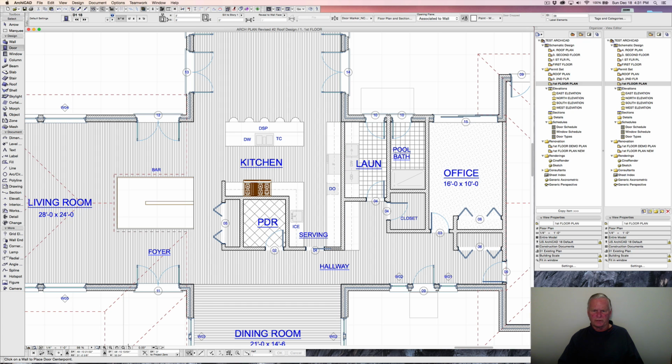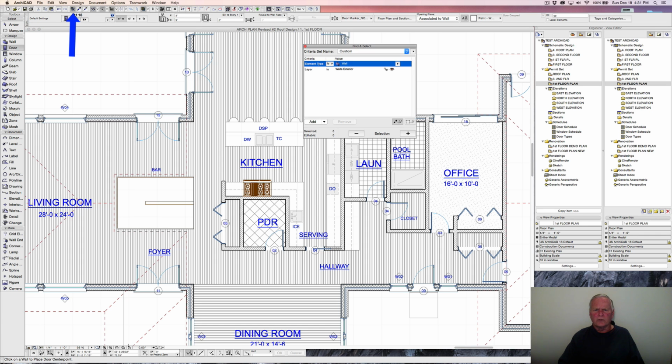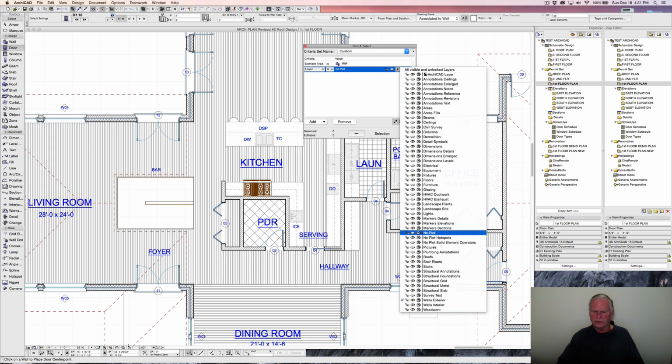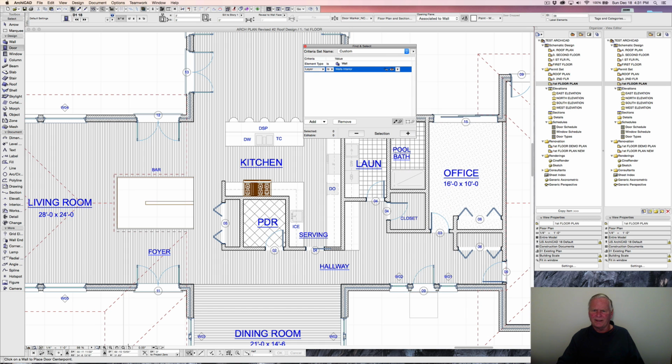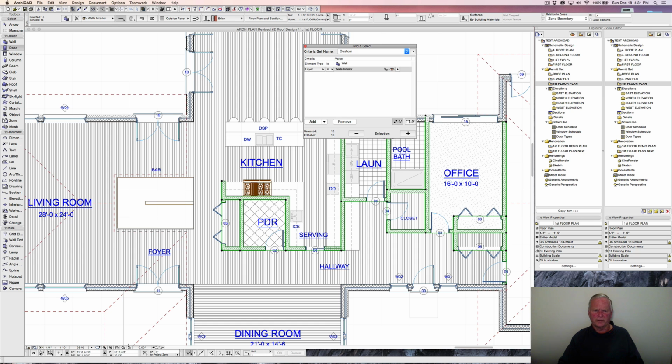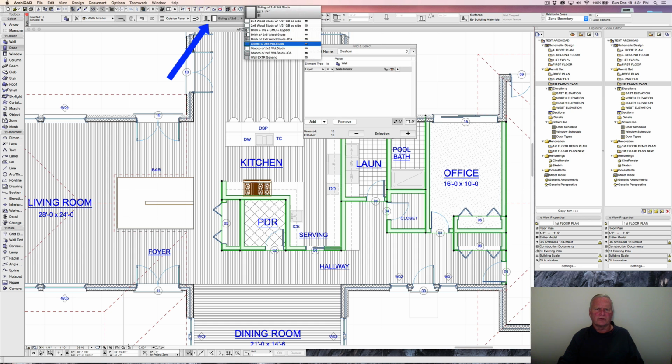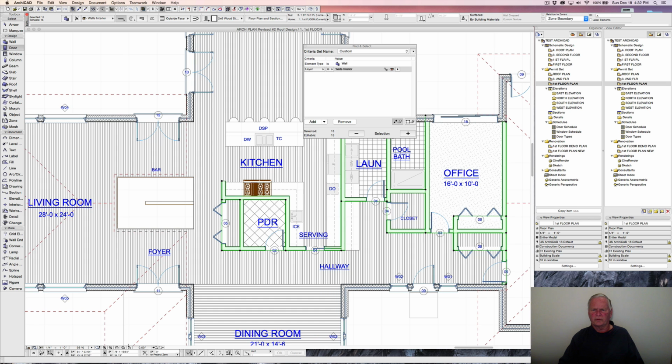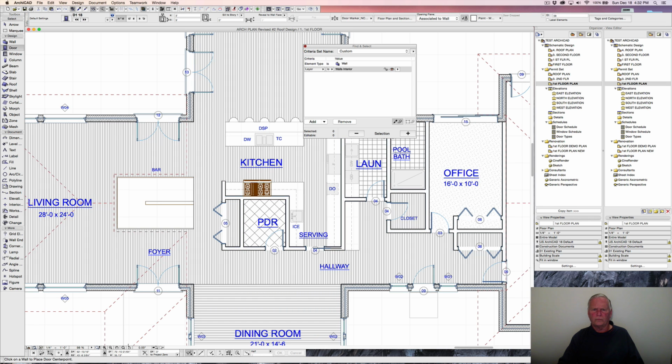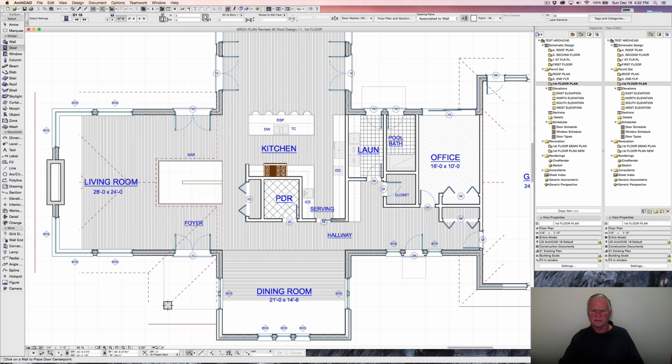And you know, one thing we didn't do on this first floor plan too is change those first floor walls. So let's just go search for walls interior, and that's all we really need to do. That'll get all our interior walls, and we'll now change them to a composite wall and select our 2x6 wood studs with half on both sides, and they'll get changed to the correct composite, and we've got that set up correctly.